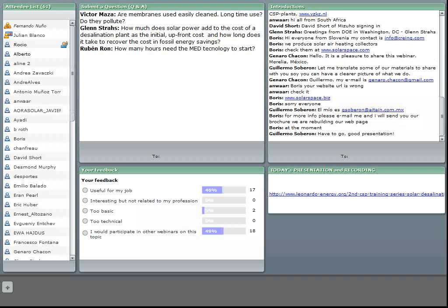So that means that you have to introduce a special configuration or special operational modes just to keep this in operation, because basically the main item that makes this possible is the vacuum. You have to create the internal vacuum in the MED, because you are evaporating at a temperature lower than 100 Celsius. So you need a specific level of vacuum, and you have to at least keep this vacuum.